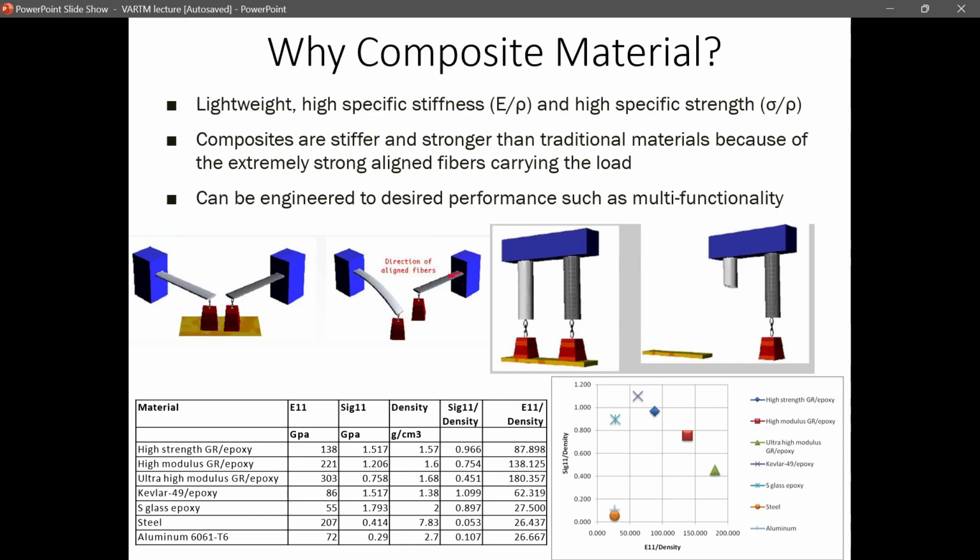The thing is, with building a composite material, you can control the stiffness, the strength, and all the material properties. You can change the material property, you can use a stronger material. As you can see here, we have 3 different composite materials, and you're going to see their modulus of elasticity in one direction is actually higher than steel. Young's modulus in some cases.